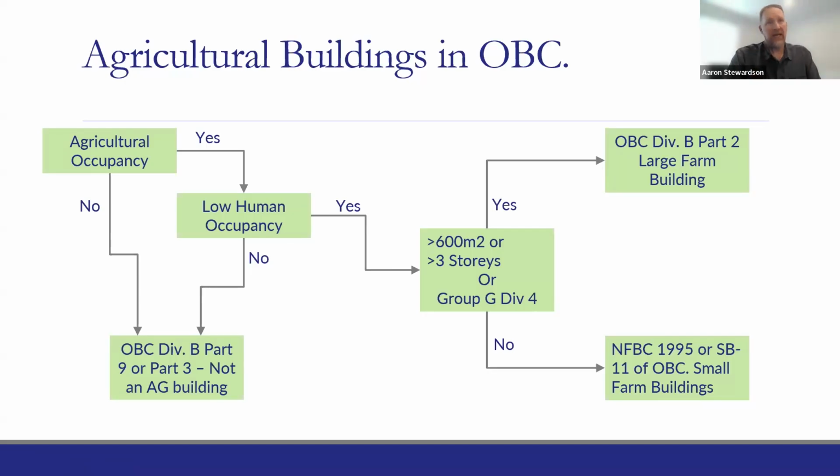The National Farm Building Code of Canada does not refer to the snow loading, seismic loading, and such under the current Ontario Building Code. It refers back to the 1997 Building Code. So when we're dealing with the National Farm Building Code of 1995, we're still using previous snow loading and seismic wind loading conditions. It's only for our large farm buildings, over 6,400 square feet, that we are going to hit the new seismic loading and new snow loading requirements under the Ontario Building Code.